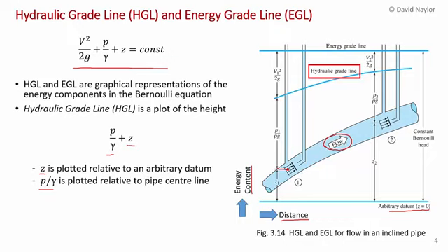We use the center line of the pipe because in these types of flows, we're representing the flow in a one-dimensional approach. So there's really only one coordinate, that's the distance along the pipe, and so the pressure in the pipe is taken as the pressure on the center line of the pipe as a suitable representative value.